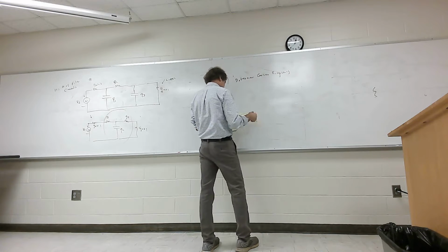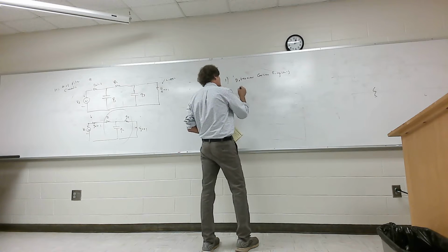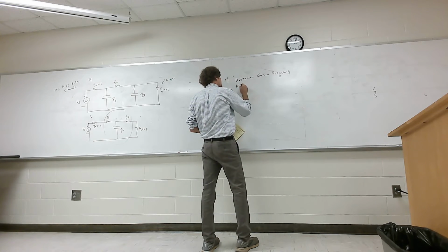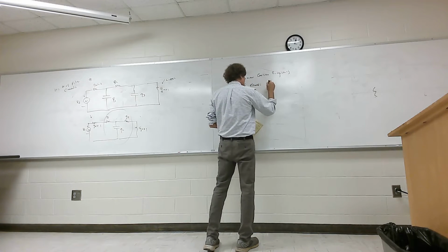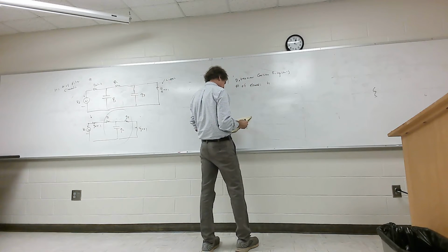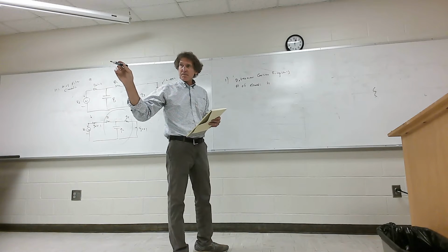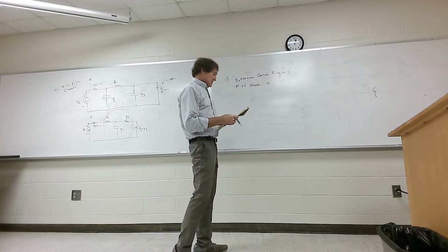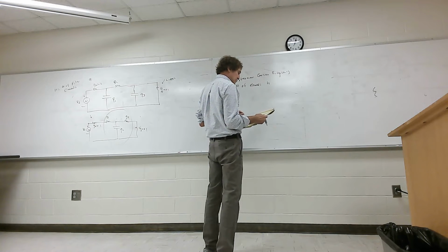Alright, and then you have to determine the number of elements you want. And that's N. After that, you go to and select the values of table 10.3. I think it's 10.3 in your book, isn't it, that table? Or is it 10.4? So 10.3. So you select the values from 10.3 and you transform the values with regard to impedance.